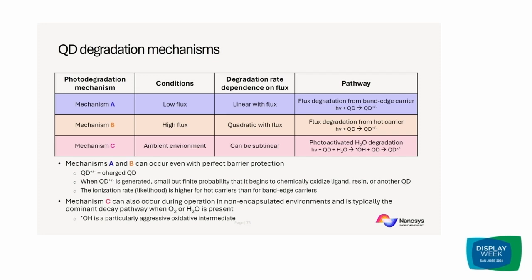So for quantum dots, there are a couple different types of mechanisms that you could imagine which degrade their performance. When they're first made, we have their peak wavelengths, we have their full widths, they have quantum yields that are almost 100%. But over time, as they operate either photoluminescently or electroluminescently, it's possible for them to lose that emission efficiency. So from decades of these studies of quantum dot reliability, it's possible to identify a few broad mechanisms of how the quantum dot can decay.